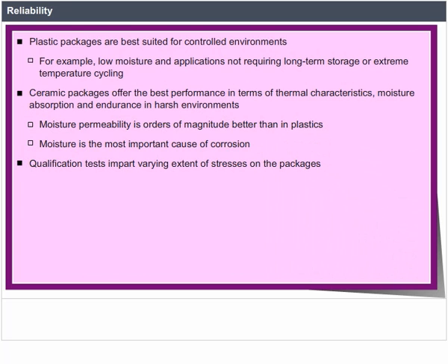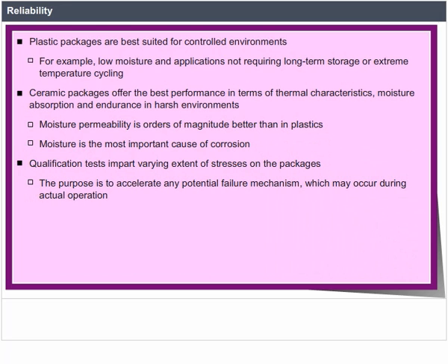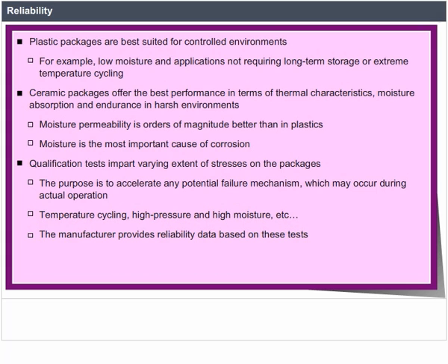Qualification tests impart varying extents of stress on the packages. The purpose is to accelerate any potential failure mechanism which may occur during actual operation: temperature cycling, high pressure and high moisture, etc. The manufacturer provides reliability data based on these tests. Fabrication process certification: QML, MIL-PRF-38535.